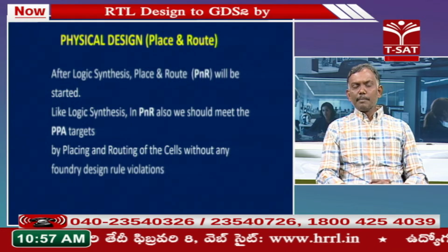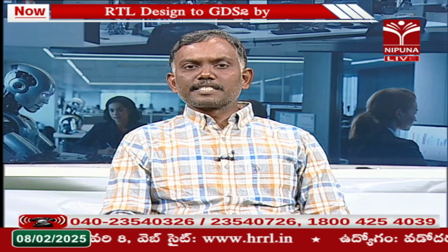We are doing timing analysis, STA, in logic synthesis; similar kind of timing analysis we need to do in place and route also, but the main impact is we are introducing net delay. In synthesis there is no routing happened.